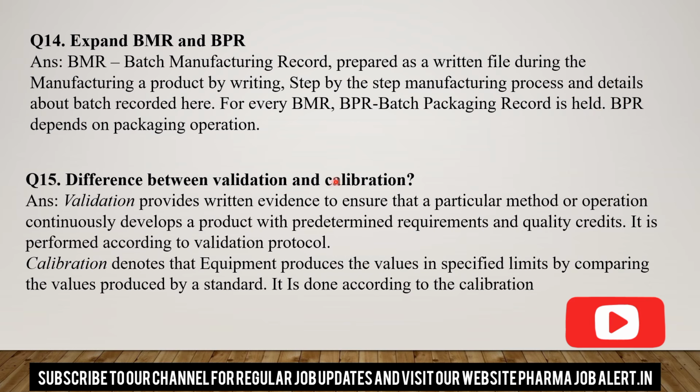So what is the difference between validation and calibration? Friends, validation will provide the written evidence, so you must highlight the point written evidence, that a particular method or operation continuously produces a product with predetermined requirements and quality attributes. Calibration denotes that equipment produces values within specific limits by comparing the values produced by a standard. It is done according to the calibration schedule.